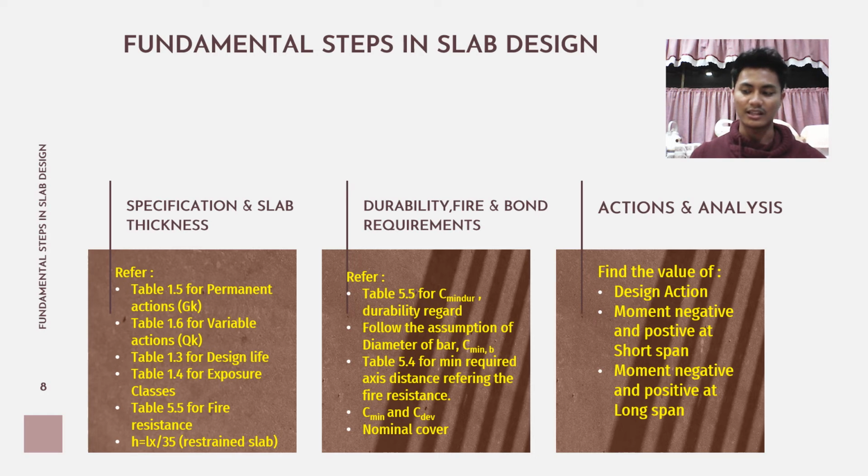So for the other 3 formulas, for the one-way slab simply supported, the formula for h is Lx over 26. For continuous one-way slab, h equal to Lx over 30. And lastly, for simply supported two-way slab, h is equal to Lx over 25.